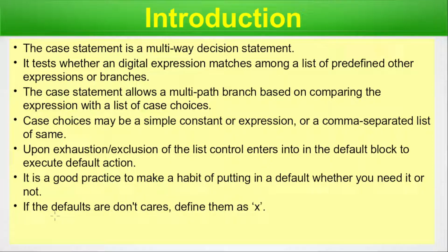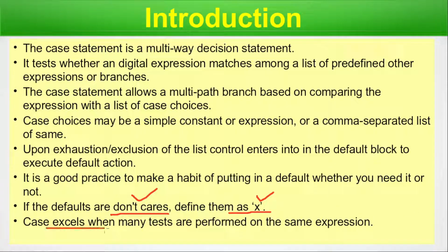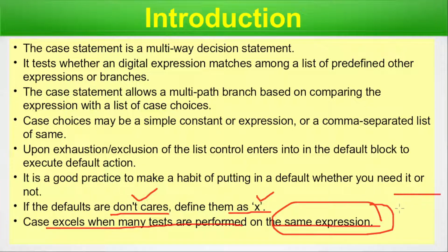If the defaults are don't cares, define them as X. As we know that in digital we have X, right? So if it is don't care, define them as X. Case excels when many tests are performed on the same expression. So if the same expression is there and the case operates on the same expression but for different values to the lookup table that we define inside the case.